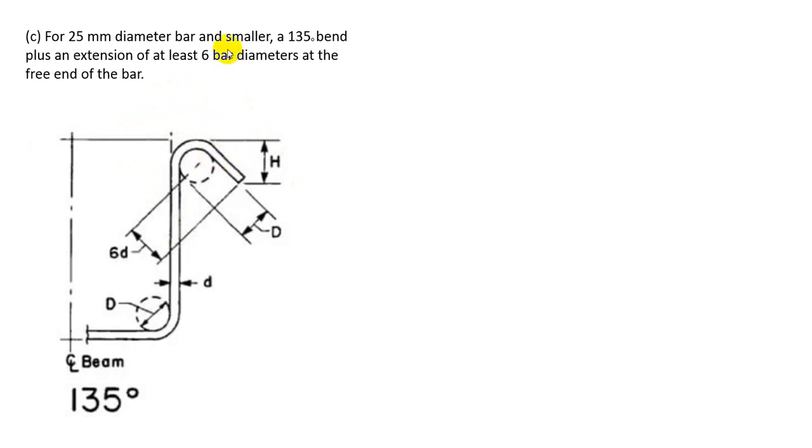After that, an extension of at least 6 bar diameters at the free end of the bar. I mean that extension should be 6D. Here our extension should be 6D.